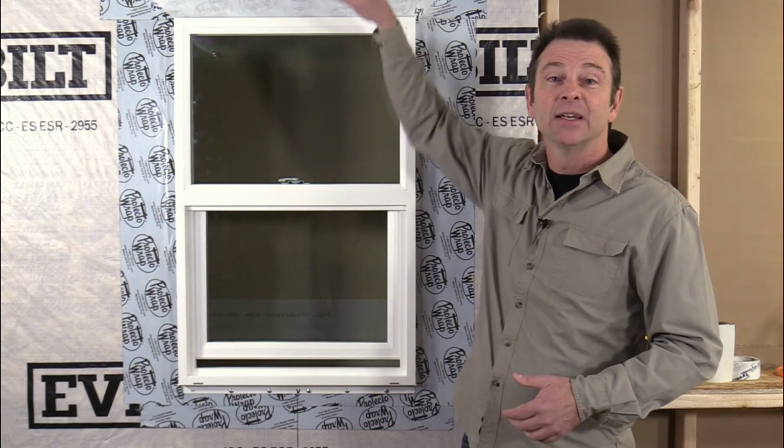Also keep in mind all of the sealing steps, from the house wrap and how that gets cut, to the caulking of the window, the sill pan to protect that bottom part of the rough opening, the flashings that help seal it up, and the final step of how that house wrap at the end will fold over. Also, don't forget your drainage plane and how all that works from top to bottom. So I hope this makes sense. Good luck in the field, and keep all this in mind when you check your windows.